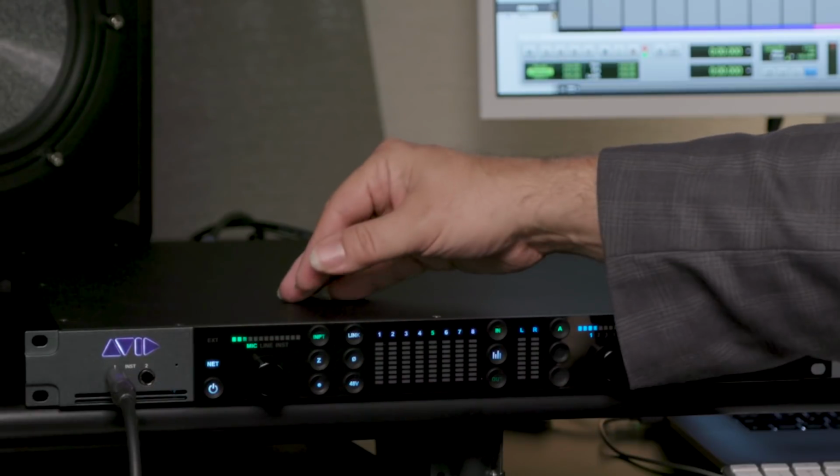On the back panel, as I mentioned, we have 8 Combi XLR quarter-inch inputs for mic and line level signals, and then we additionally have those 8 line level signals showing up on a D-sub as well. So this allows us to, say with a patch bay, have 8 microphone level inputs configured, 8 line level inputs configured simultaneously, and then select among them just using the input switch. 8 line level outputs are also on D-sub connector, and then we have our dedicated monitor outputs.